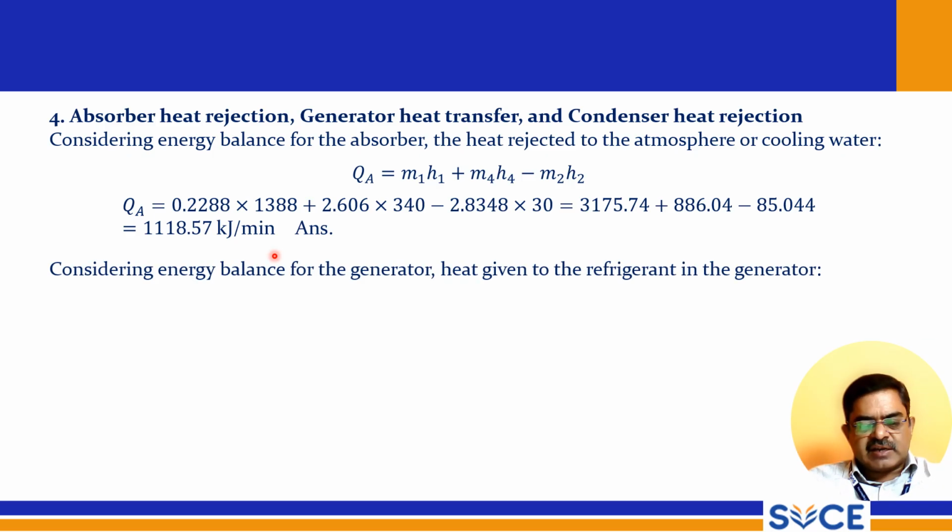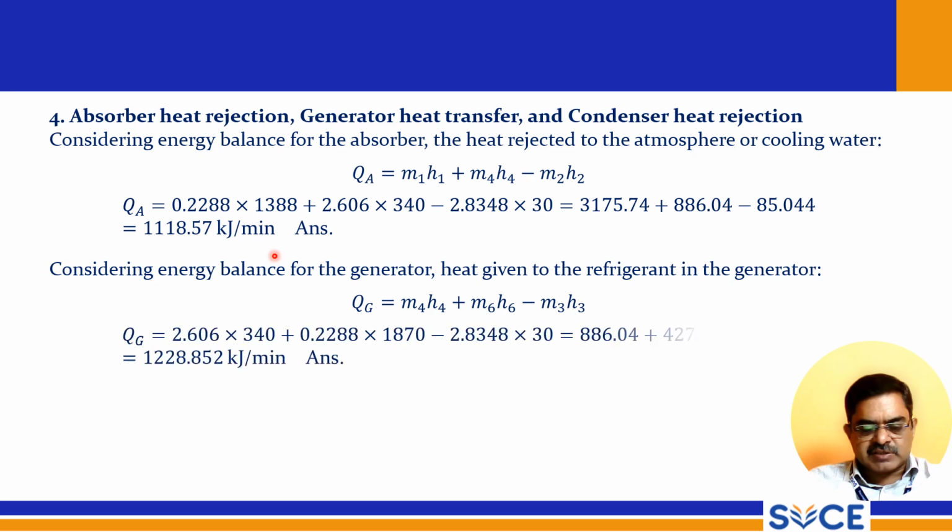And considering energy balance for the generator, heat given to the refrigerant in the generator is Qg. The same mass equation is used here, M4H4 plus M6H6 minus M3H3.